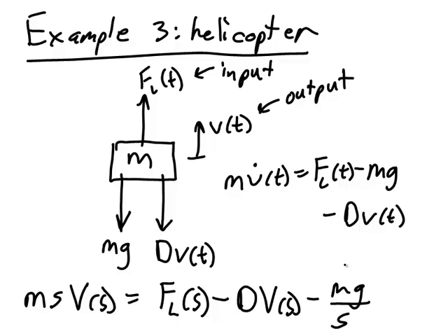In this problem, one way I can deal with gravity without having it be its own term is by lumping it in together with the lift force. In other words, if I define the lift force as being the lift force that is in excess of gravity, then I do not need to account for the gravity term.